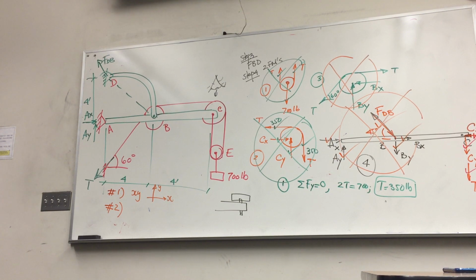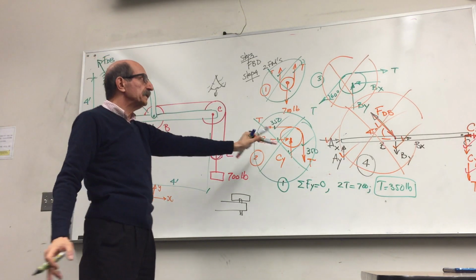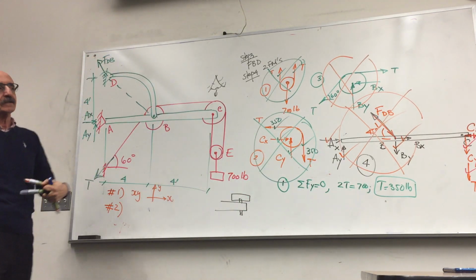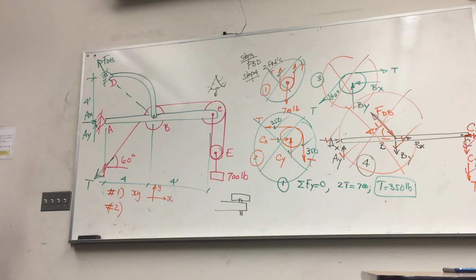I noticed you didn't do a free body diagram for the 2-force member. Do we need to do that? You mean here? No, I didn't, because, as I said, a free body diagram for a 2-force member doesn't give you anything. So we shouldn't necessarily include that? You don't have to, but be careful though, what is more important is that 2-force members represent just one unknown force as you do the other diagrams. Yes, was there another question?